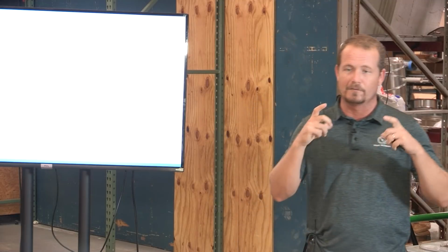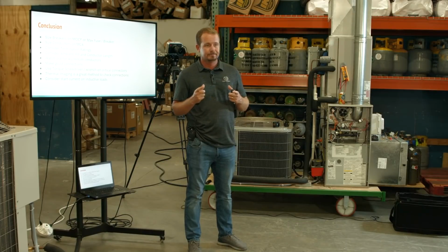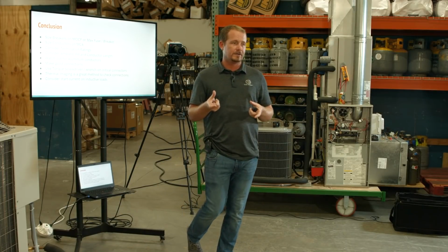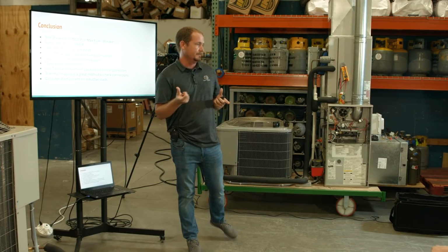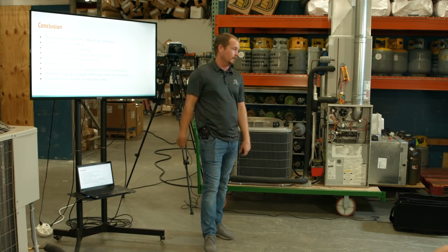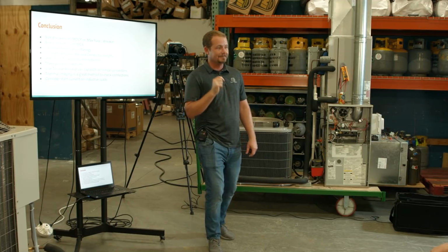Now be careful, those of you who get your little FLIR or whatever brand you get, and you use it the first time and go into a residential panel, you'll find that some breakers get really hot. Do you know which ones get really hot? Arc fault breakers. Arc fault breakers are just hot by nature because of the internal whatever fancy magic inside of them. I'm really prepared to describe the internals of an arc fault, as you can tell. It's the fancy hot magic inside there that makes them just run hot all the time compared to their neighbors. And that's what you use the thermal imaging camera for.